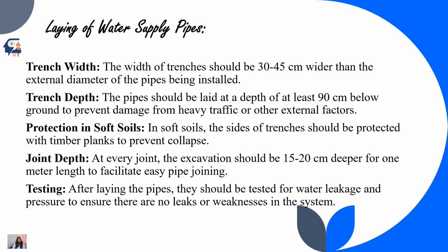Lastly is testing. After laying the pipes, they should be tested for water leakage and pressure to ensure that they do not cause any weakness to the system, and that there are no leaks and cracks developed.